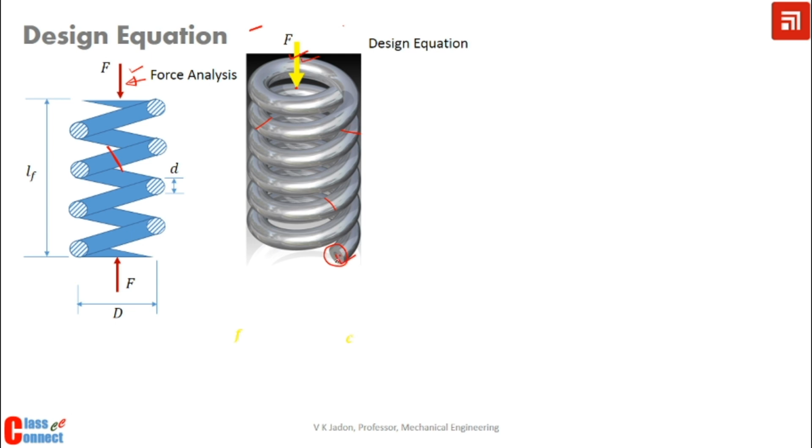For that, we have to apply first equal and opposite force where we want to see the effect, and then we have to replace this force and this force with a couple, and this couple is this. So finally, if we see the resultant force on the spring wire, we can see that the final force that will remain is this force in this direction and this couple.